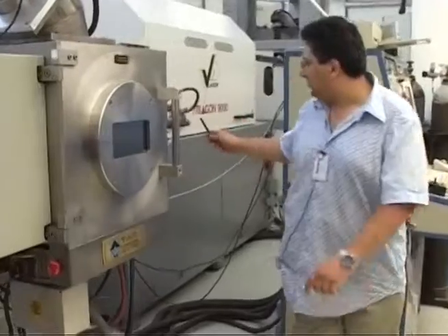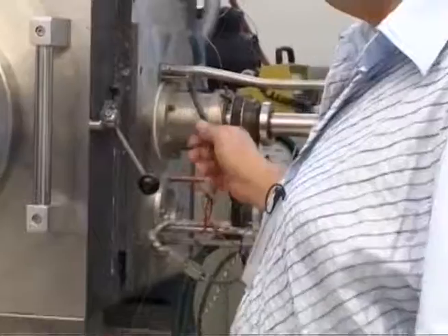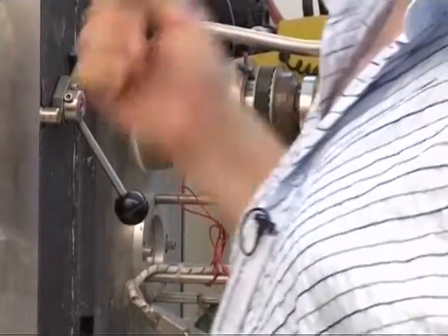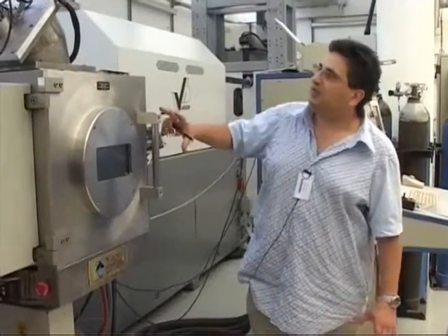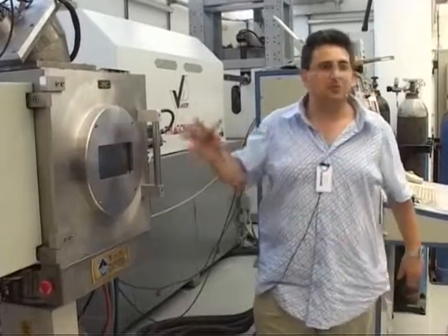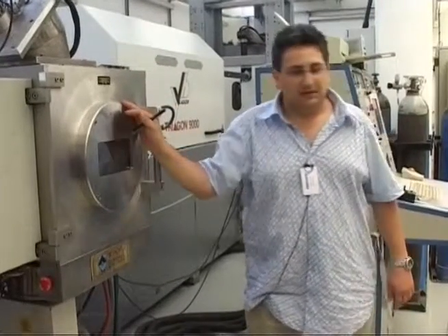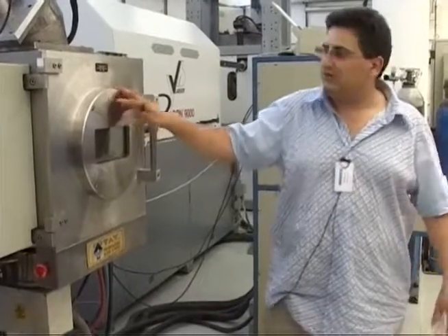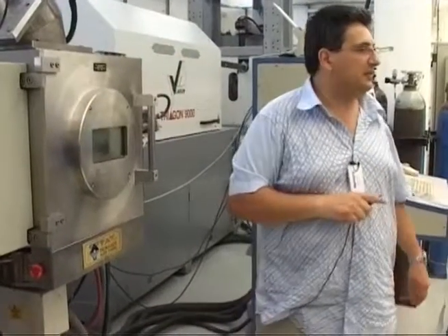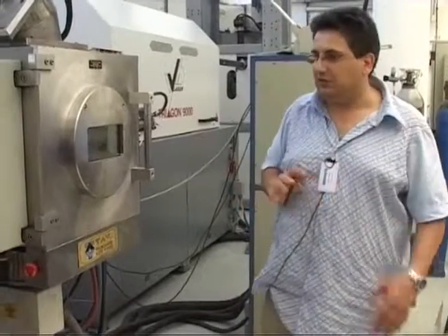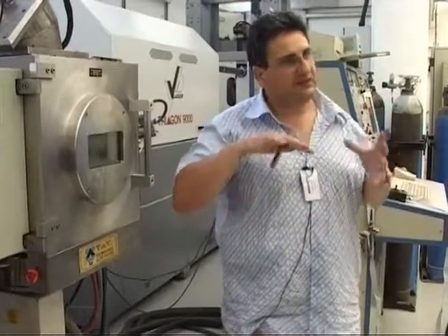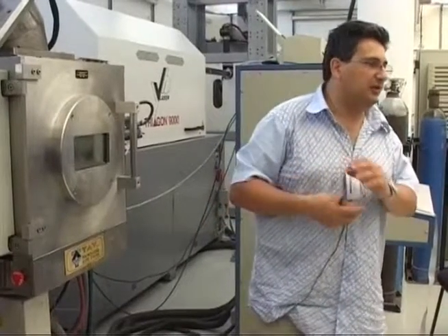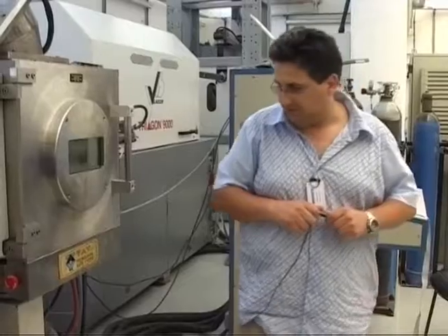At the far end of the chamber, we have a rotary water-cooled table which manipulates the components in such a way as to expose all the facets of the components to the ion beam. This technology has a big disadvantage in which the ion beam travels in a straight line. And in order to treat the component from various sides, we have to manipulate the component continuously.